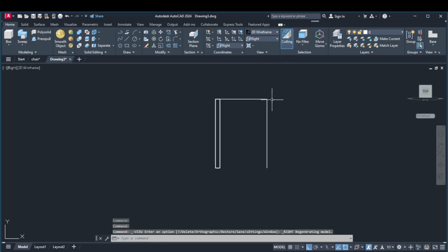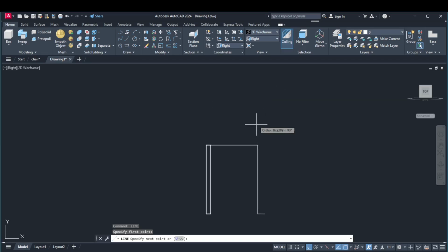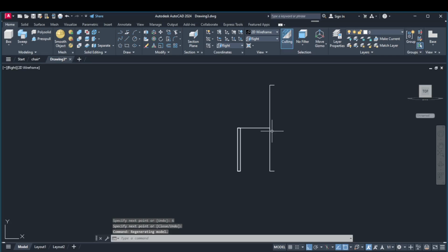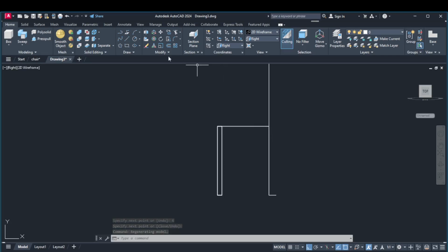You have this. So we pick a line, then you can just move towards this side 6, enter, enter, then moving upwards a distance of 60, enter, then towards the other side 6, enter, enter. We can also have, from this center of ours, a slight distance before that slanting begins.